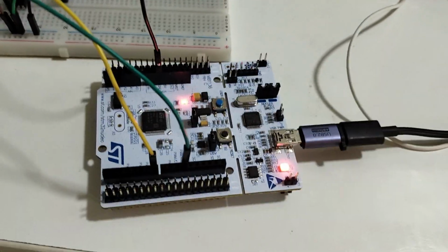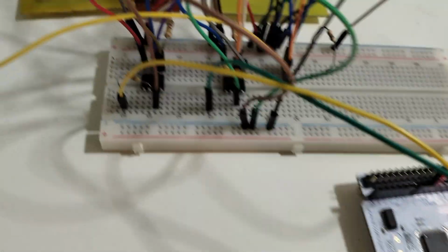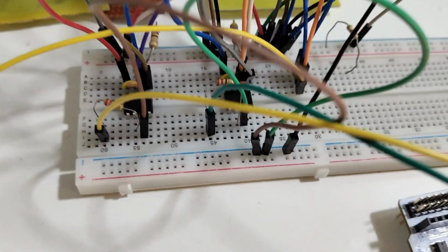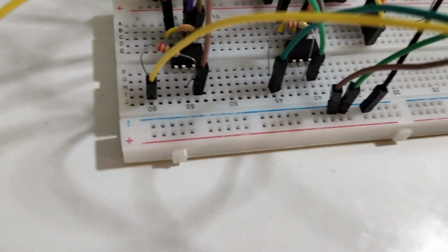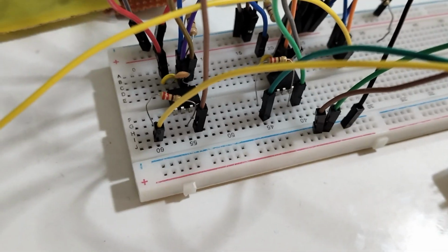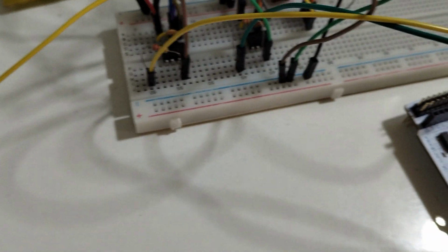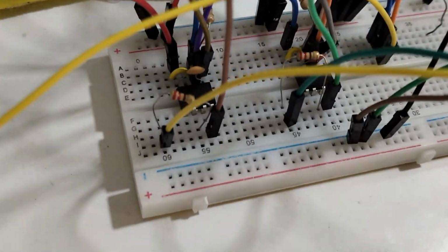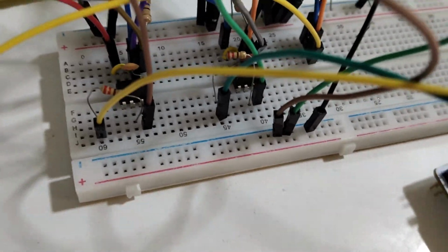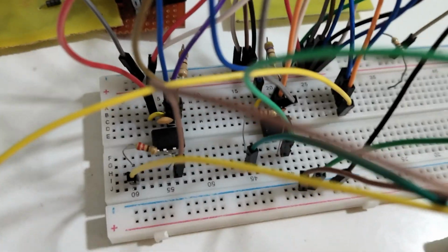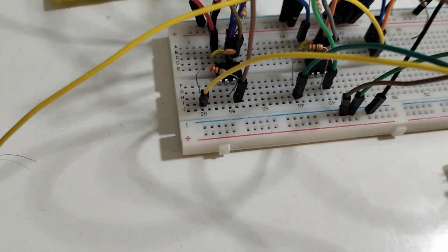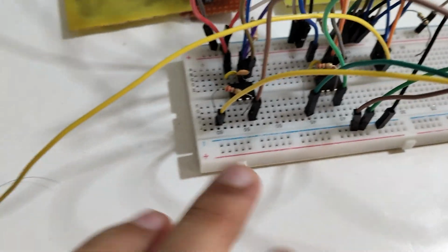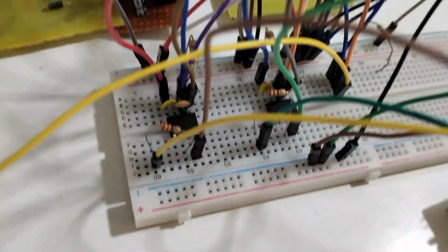So I have my microcontroller board here, and I did not mention it in the video, but since I'm doing just open loop right now, I have put these optocouplers here, and you can see the earlier video on it. It just provides isolation to protect your microcontroller from the power circuit. Since we have two PWM signals, I have two optocouplers here, the 6N137s. These are high speed optocouplers, and you need high speed because we're switching at a couple of tens of kilohertz, so don't use the slow ones, they'll destroy your PWM signal completely.